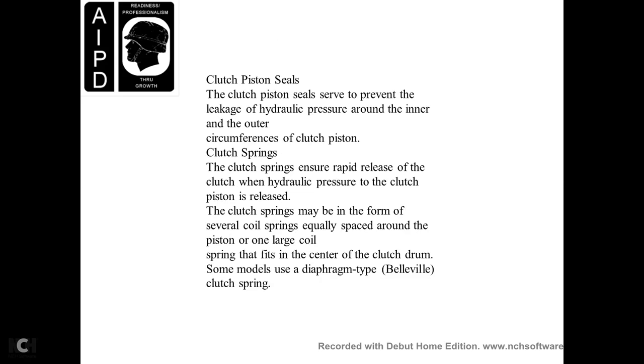Clutch piston seal: the clutch piston seal serves to prevent leakage of the hydraulic pressure around the inner and outer circumference of the clutch piston. Clutch return springs: the clutch springs ensure the rapid release of the clutch when the hydraulic pressure on the clutch piston is released.